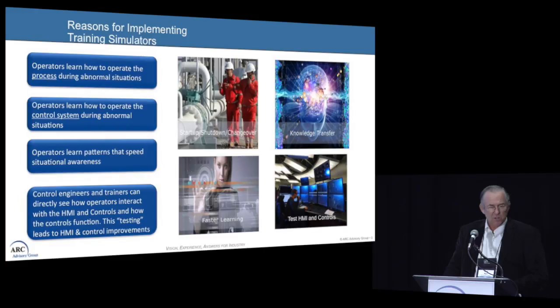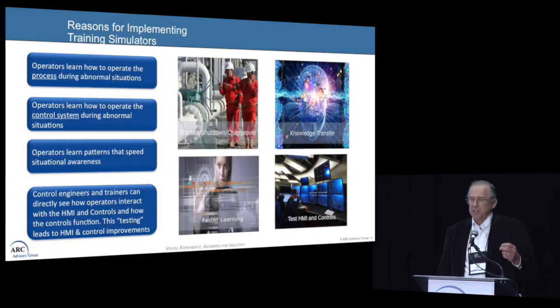So what are the reasons for implementing training simulators? A lot of times people think the only main reason is that we need operators to understand how to operate the process and the physical equipment. We need them to know what temperatures to regulate at. We need to teach operators how to start up and shut down the process. But a good part of the training simulator's capability is to teach the operator how to use the control system.